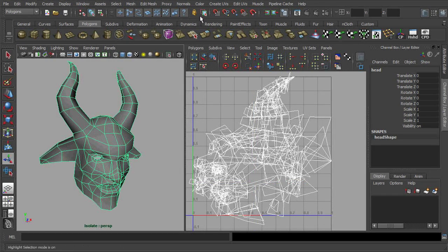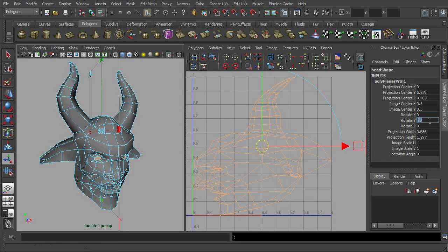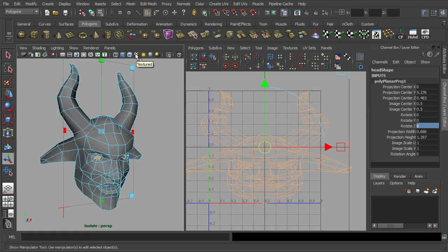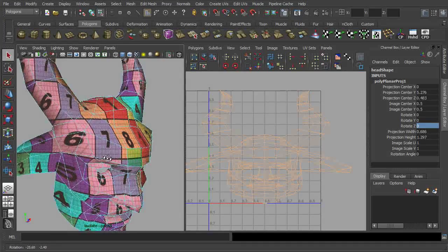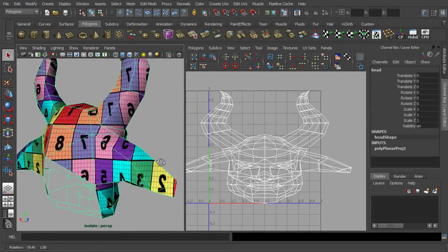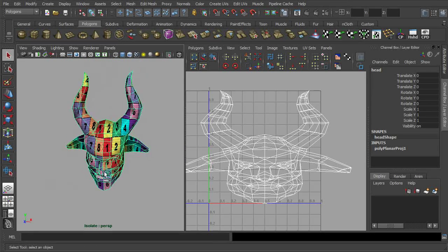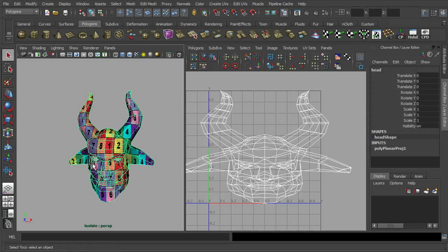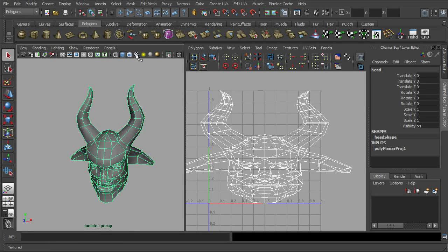First, let's clean up all the fragmented elements with a simple planar projection. In the unwrapping process of an organic character, we cannot fully rely on the ready-made preset like planar mapping, as it would not fit the topological flow of a mesh. Distortion is inevitable in most organic matter, and the effect is most drastic in a low-poly mesh, but we could minimize it with the right techniques.